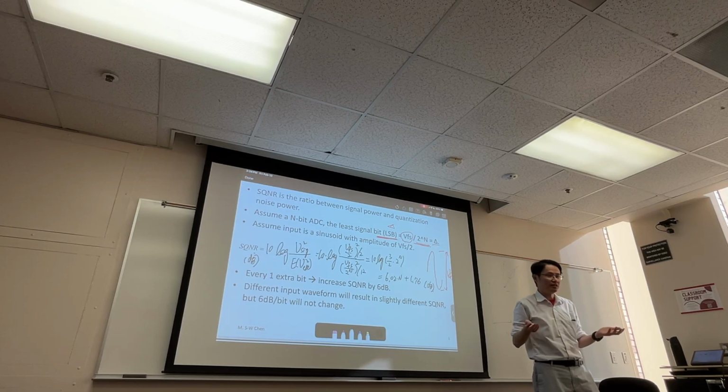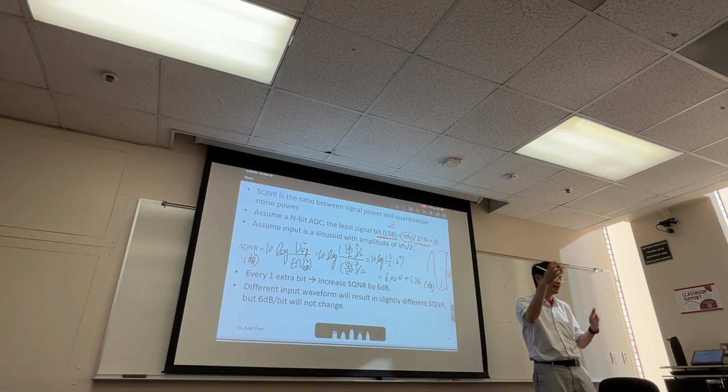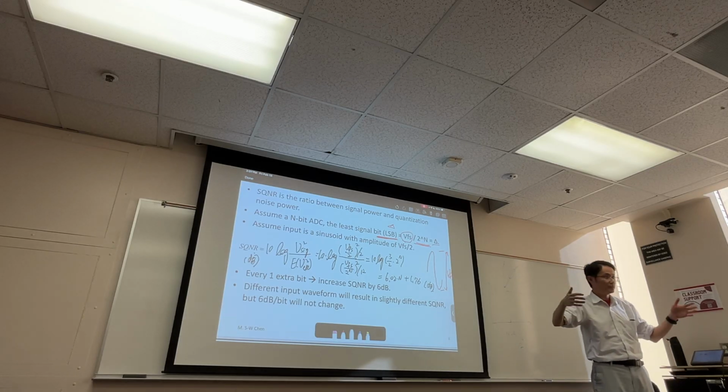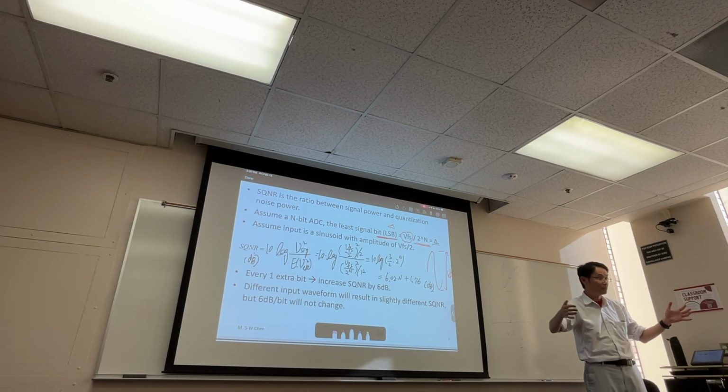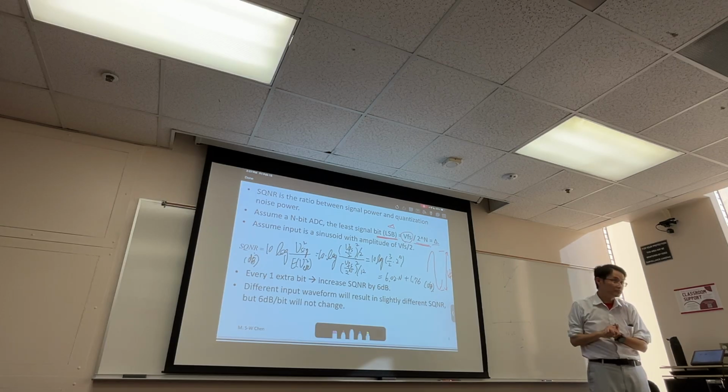It doesn't mean that, hey, I cannot do somewhere in between. Who said that you cannot design 600 steps? Who said you cannot do 700 steps, right? That will be somewhere in between. So then you design an ADC that is 9.5 bits or 9.6 bits. You are right, the actual output will probably be 10 bits wide. But if you compute the actual SQNR, you will only get 9.5 bits or 9.6 bits. So it really depends on that conversion level, right?